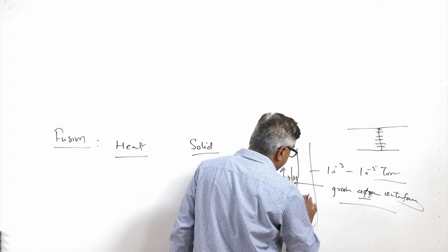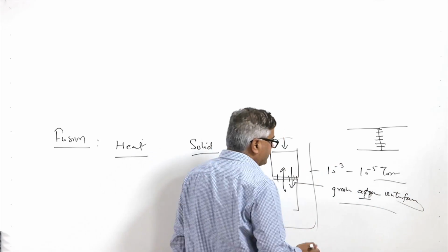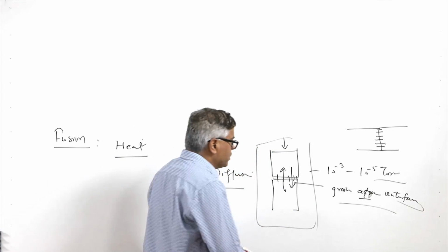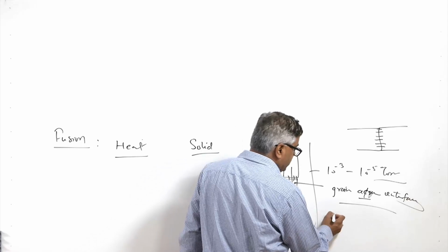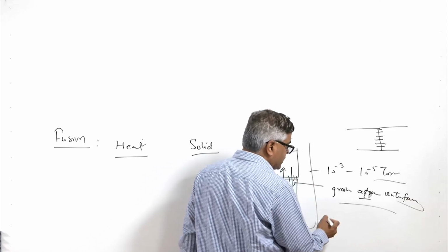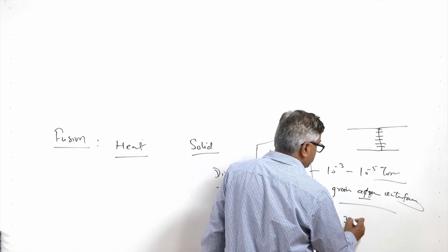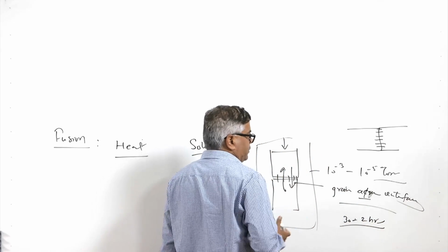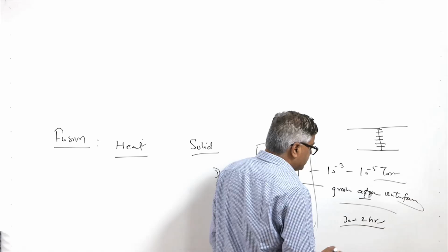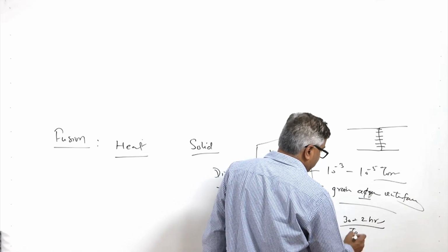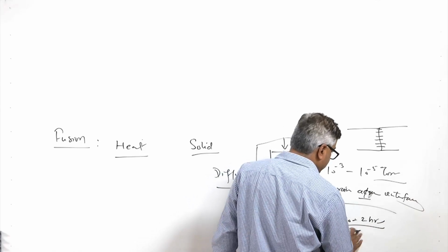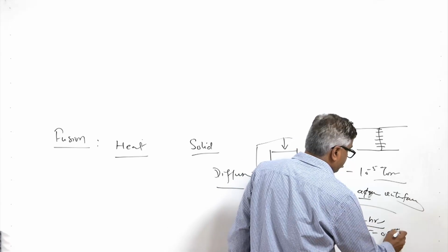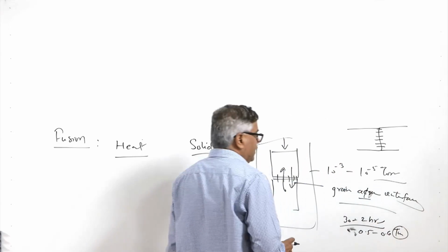So, heating is important to facilitate the diffusion, since the diffusion is a slow process, so it takes time. So, we need to provide enough time so that diffusion can occur across the interface. Normally 30 minutes to 2 hours time it takes to have the kind of metallurgical continuity across the interface, and the temperature can vary in the range of say 0.5 to 0.6 times the melting point of the metal in Kelvin.